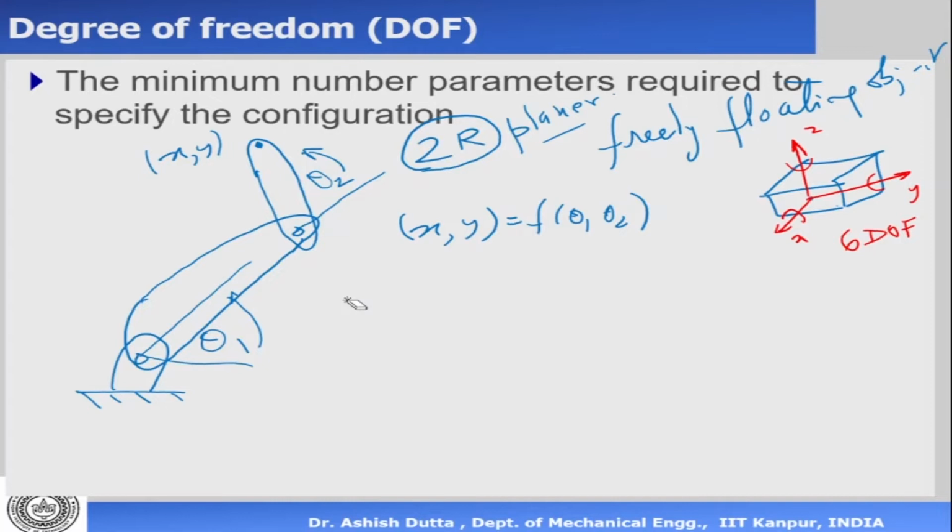Okay. Now, suppose I add a gripper in here. Say I'm putting one gripper here like this. So this is a gripper now, and this gripper angle is now my theta 3 here. Then we can say that the final angle that the gripper is making, phi, is a function of theta 1 plus theta 2 plus theta 3. Okay, or theta 1, theta 2 and theta 3.